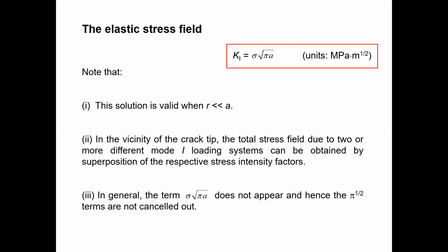If you remember, we already did this for the K value as well. K f, when you are going to find out for bending, you will find out the K f value for bending, and the K f value for the axial load, the K f value for torsion, likewise. So we call this theory the superposition principle, superposition theory. That means those values are independent. So the K a value, the K f value, the fatigue stress considered value from bending, is independent of the torsion. The torsion is independent of the other two, like that.